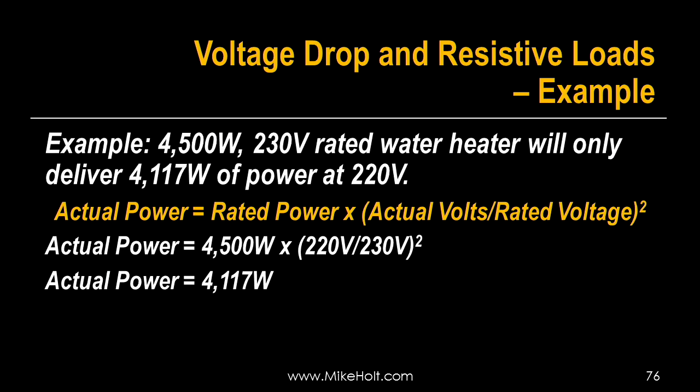Where this really comes into play is a 240 volt heater working on 208. That's 75%. So a 10 kW heater rated at 240 is 7,500 watts at 208. Did you follow what he just said? Let's see if that's true. Let's do the math.